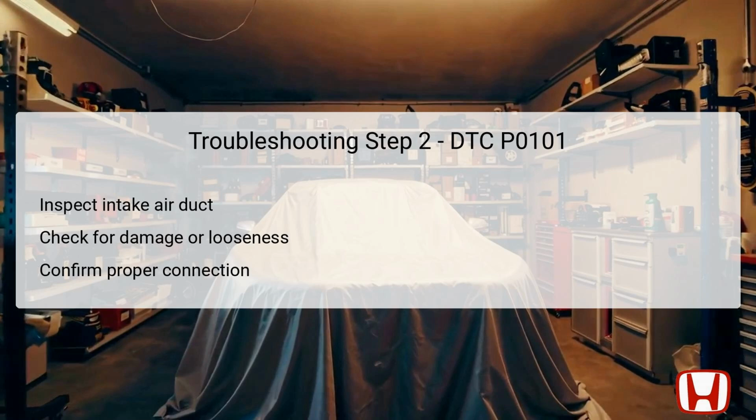If the duct appears damaged or loose, it should be reconnected properly or replaced to restore the integrity of the air intake system. Conducting this check is essential because it can directly affect how air enters the engine and consequently how the MAF sensor measures that airflow.